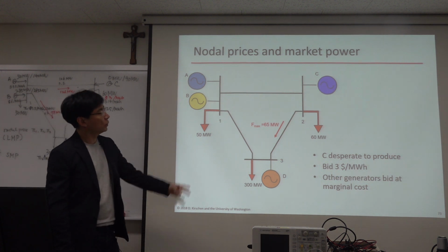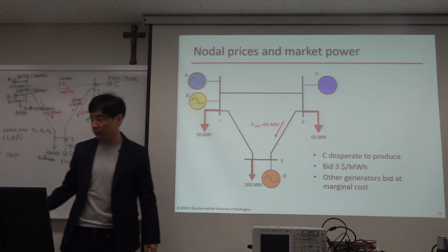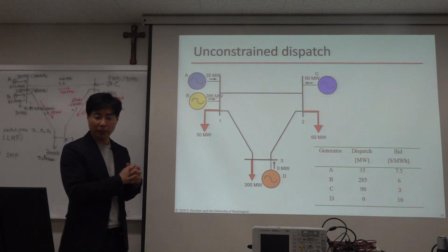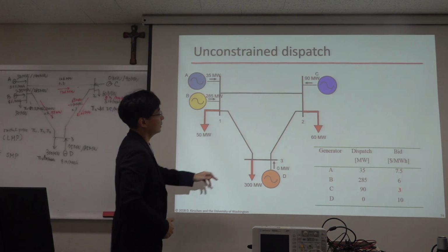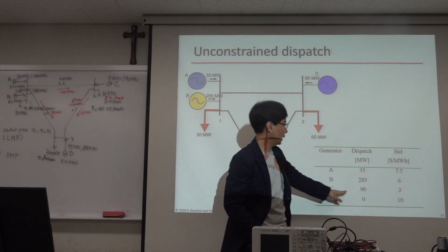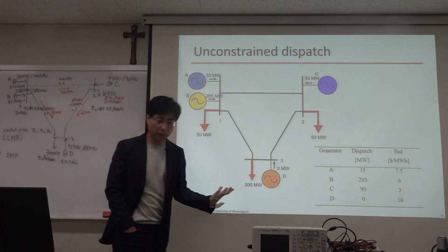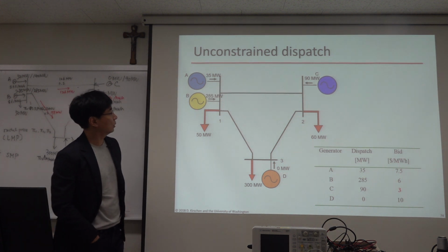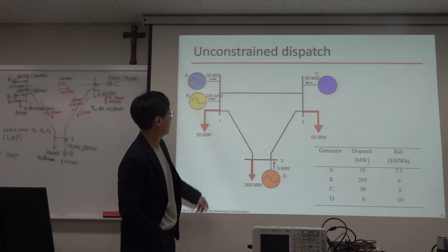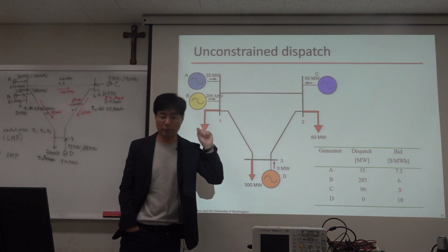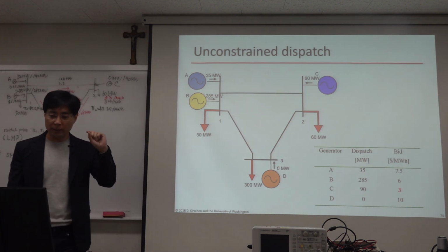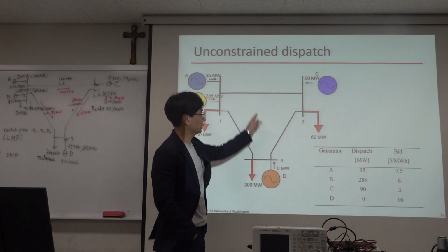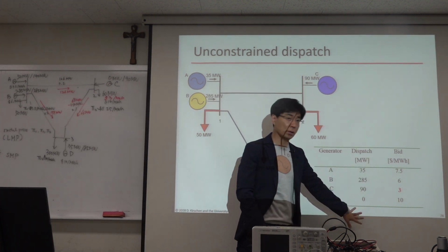So when these two things have changed, to do that, first, because the marginal cost of this generator has changed like that, you need to solve economic dispatch. The total load is 300 plus 50 plus 60, so 410. What is a combination that satisfies this load using generators having this cost?